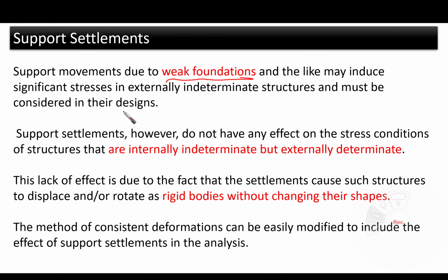Because we are talking about indeterminate structures, our structure is not going to tolerate any kind of deformation or movement due to the weak foundations. So this is why, in the case of an indeterminate structure, it is very important to consider support settlement or movements in general.